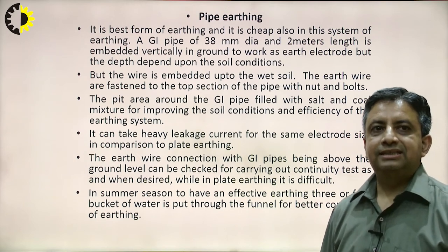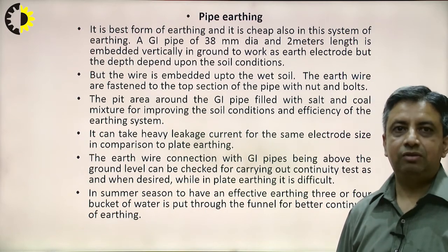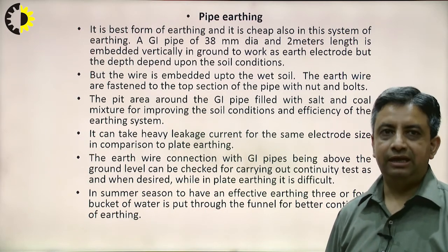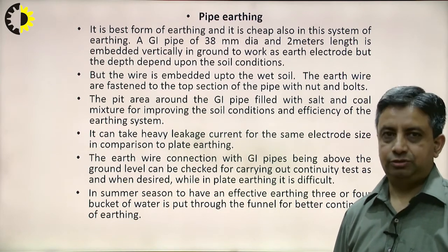So in this case, the wire is embedded up to the wet soil. Again, that is a basic requirement, because we know that to maintain conductivity, we should embed that wire up to the wet soil.